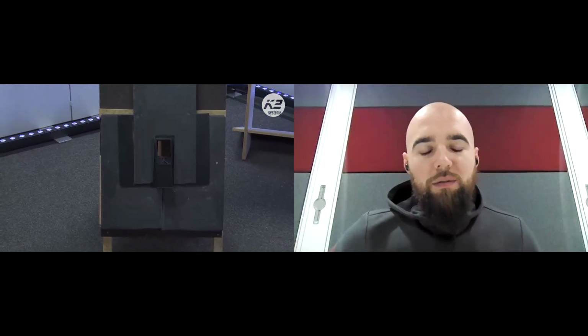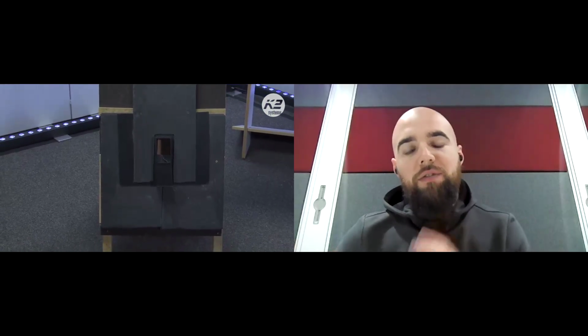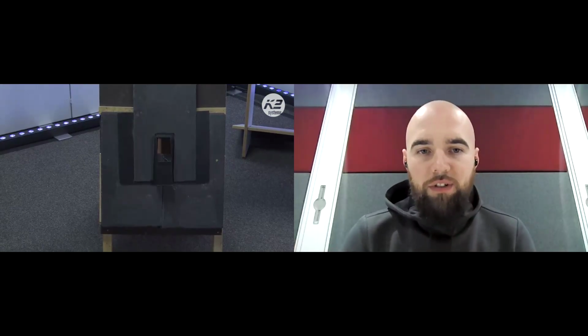So you can see there where it doesn't require the tile to actually be moved, because you can see straight through the rafter. With the older flashing that Genius Roof Solutions had, you'd need to take off that top tile so that you could actually get to the rafters below. So it's just increasing the speed really. Obviously, with the more generic flashing kits that you can get out there, like the flashing, the lead rolls and stuff, you'd still need to remove that tile. So obviously the speed increase is well welcomed.